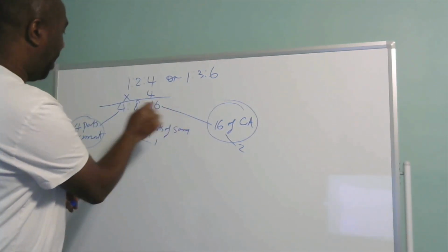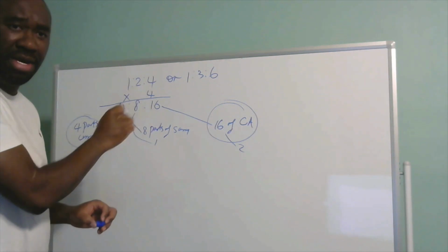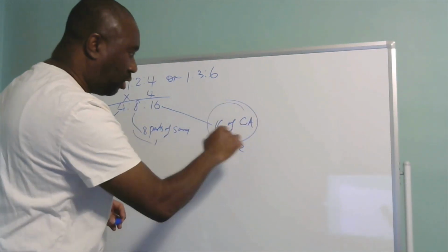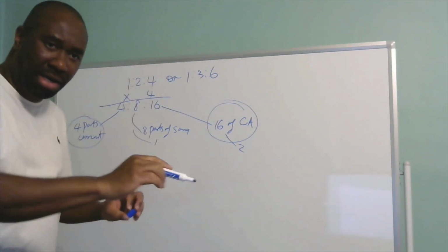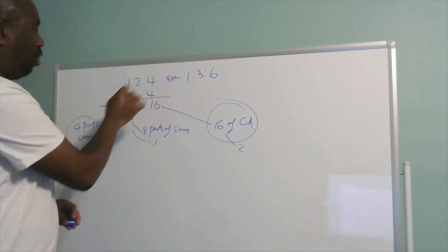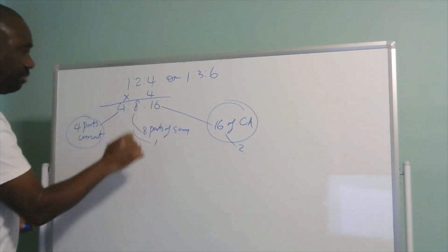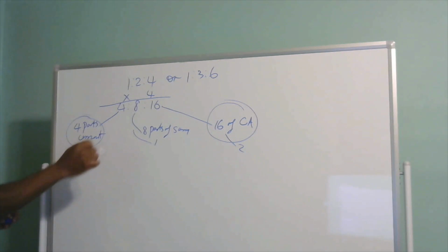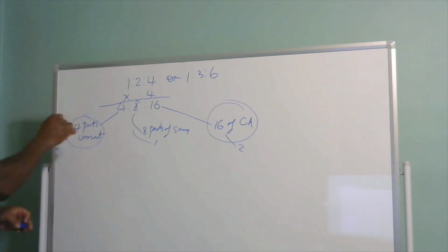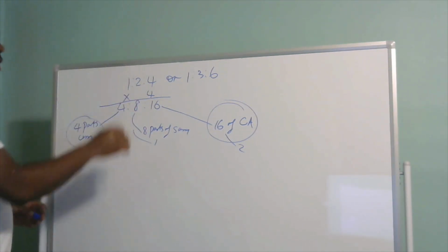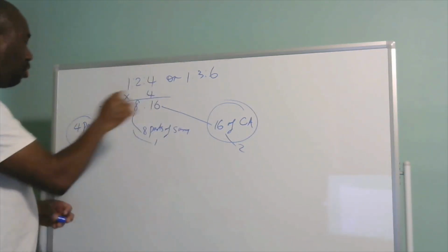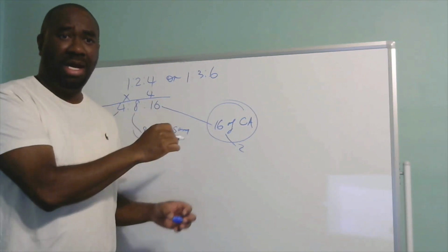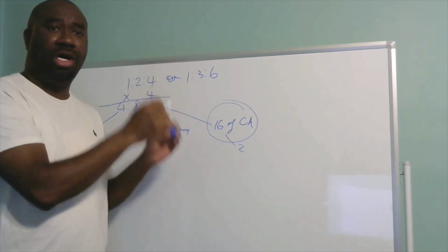You're supposed to mix up the sand and the cement first, you level it out, and then you run on your coarse aggregate, and then you part the middle, you put in the water. Because when you run on your sand and your coarse aggregate, and then you put on the cement on top of that, when you part that middle and the water starts to run, it's going to take away the cement from out of your mix, and as a result, weaken your concrete mix.